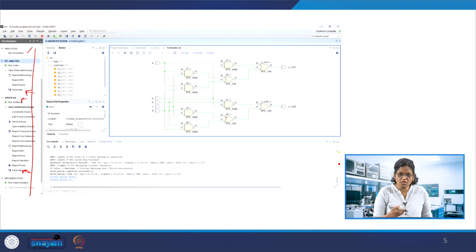So based on the technology, this would give us the view of whether your Verilog module uses LUTs, registers, latches or muxes, what multiplexers it is using. Those details will be given, and this portion will be changed to the technology specific view. So that we would see.